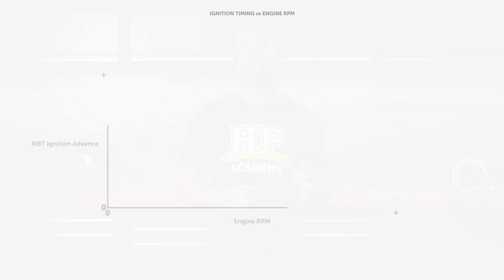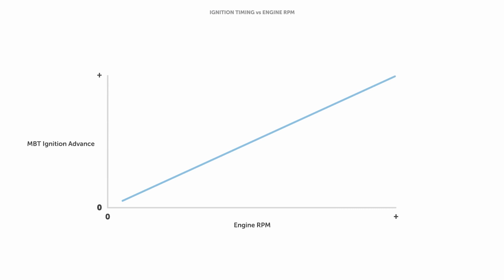Here is a graph that shows the general trend that we get. As the engine RPM increases, we see a trend where the ignition timing advances. The other trend we see with ignition timing is that it will vary with the amount of load the engine is under, or to put it another way, the amount of air and fuel being combusted.